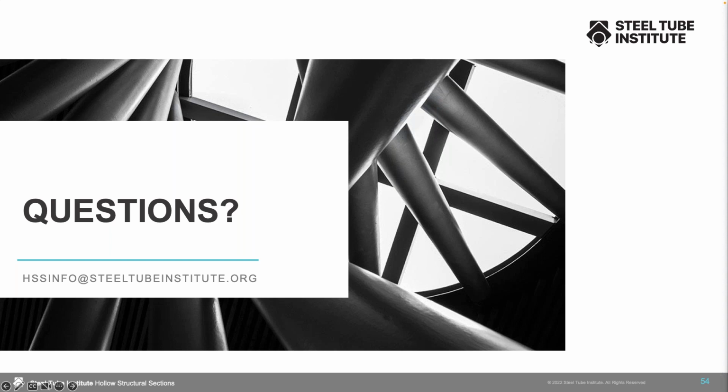The first question that we received is, is ASTM A513 a pre-qualified base metal in the welding code AWS D1.1? And the answer is no. ASTM A513, which Beth had discussed, covers many of the very small tubular sections, oftentimes used for handrails and miscellaneous steel components and such. That A513 is not on the list currently of pre-qualified base metals in AWS D1.1. And for reference, that's Table 3.1 in the AWS code.